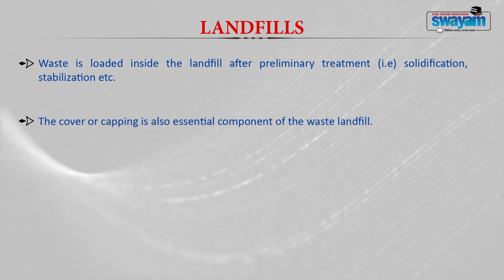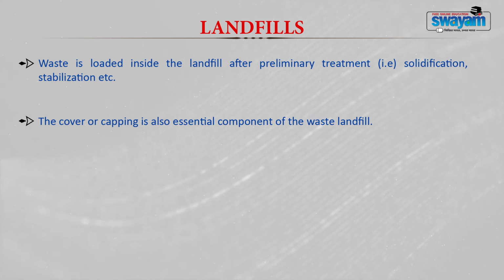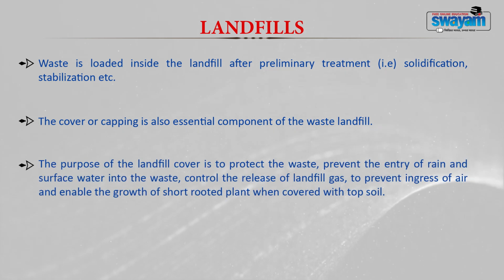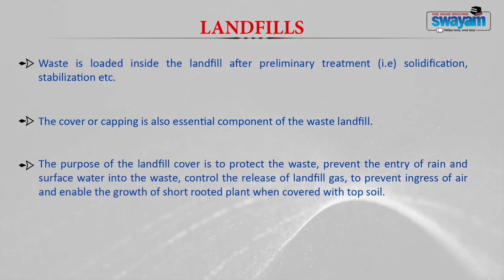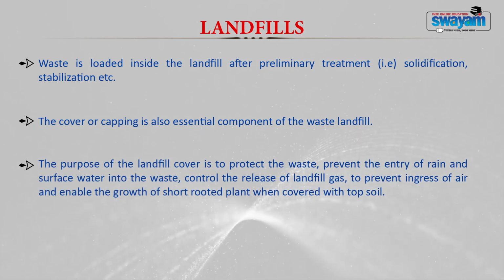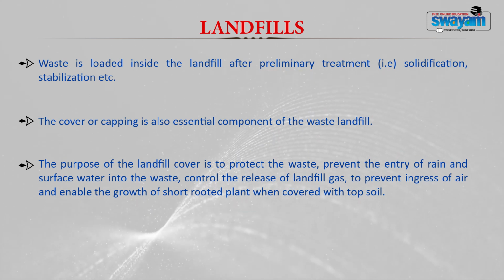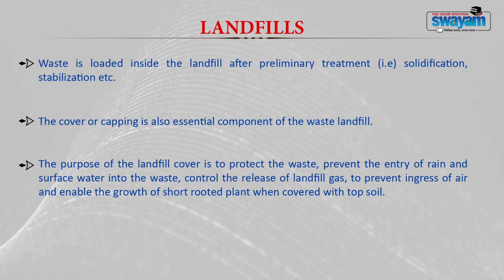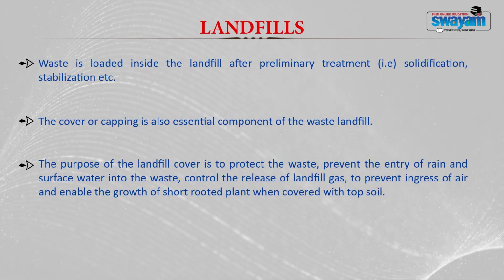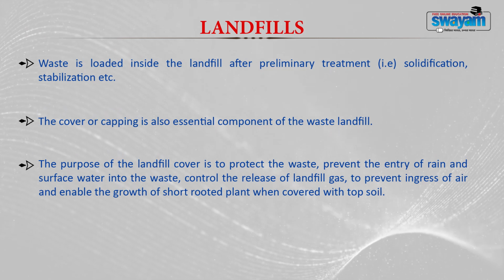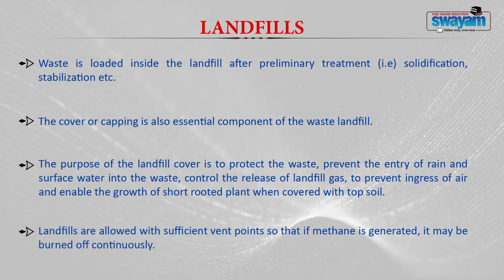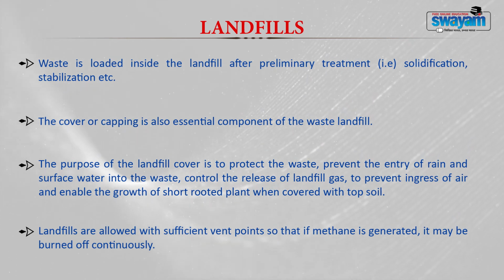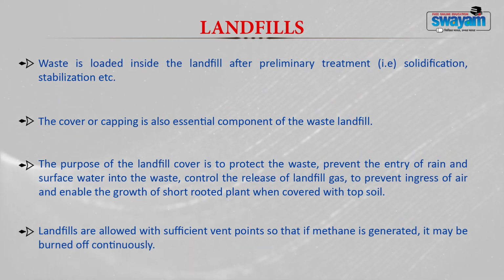As I told you, the third component is your cover or capping, which is very essential to contain your waste in the landfill. The purpose of the landfill cover is to protect the waste, prevent entry of rain and surface water into the waste, control the release of landfill gas, to prevent ingress of air and enable the growth of short rooted plants when covered with the topsoil. Now, landfills are generally provided with sufficient vent points so that if methane is generated, it may be burned off continuously.